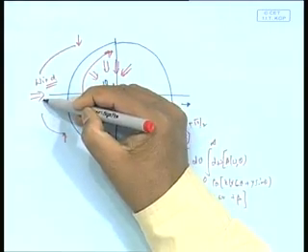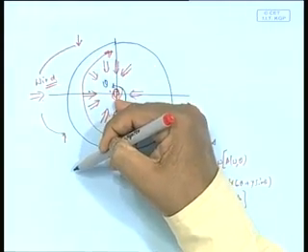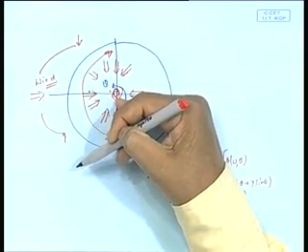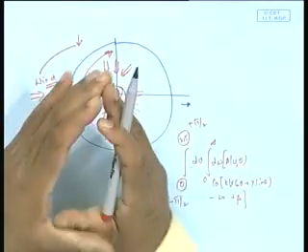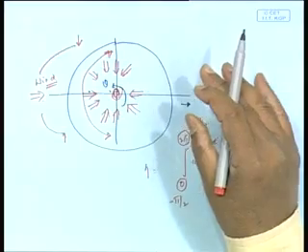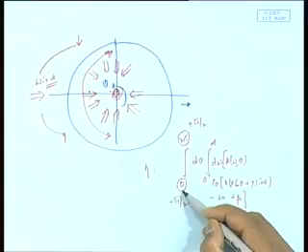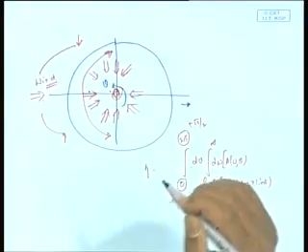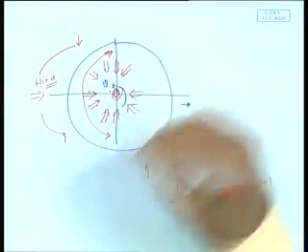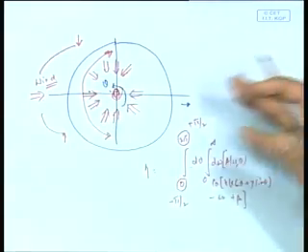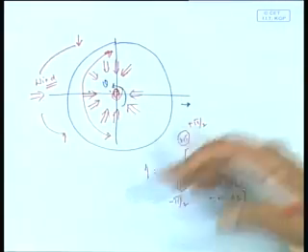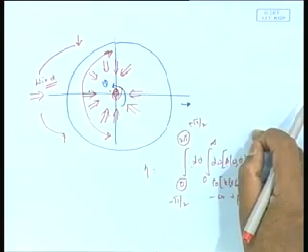So if I take this as base, then the waves lie from minus pi by 2 to plus pi by 2. I would have the most dominant, very high wave in the direction the wind blows, and there will be other waves coming on both sides, with a 90 degree split. That is more logical. After all, I am only looking at the integration. So if I take 0 to minus pi by 2 and 0 to plus pi by 2, with 0 being the direction of the wind, it makes more physical sense, and of course it satisfies my property also. So typically this is done.